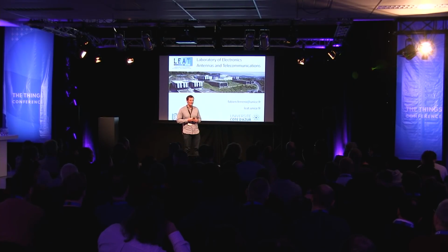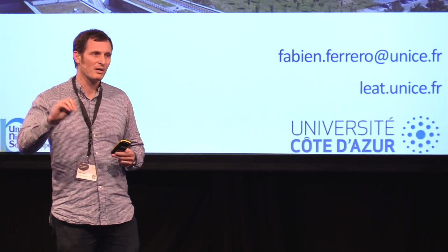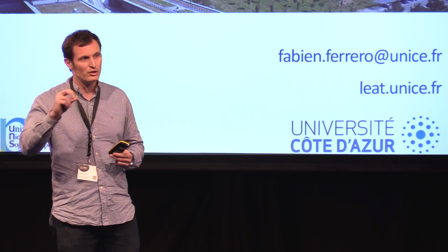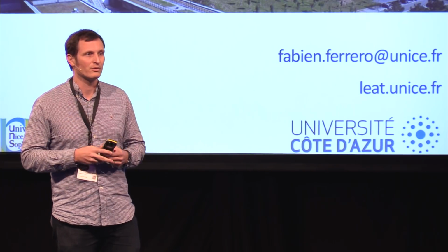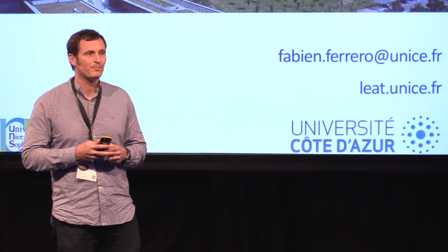No easy solution. I know that, for example, in Switzerland there is a company, Spiag, that has a solution to measure the input impedance of an antenna using optical fiber. With optical fiber, you get galvanic isolation, so you don't have the shield of your cable, and then you can measure it accurately. Thank you. Okay, thank you.